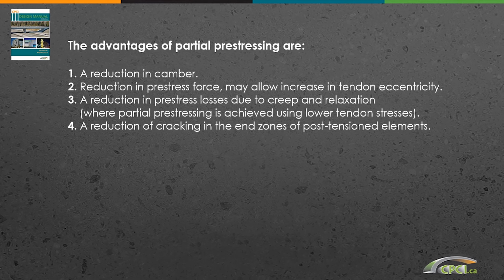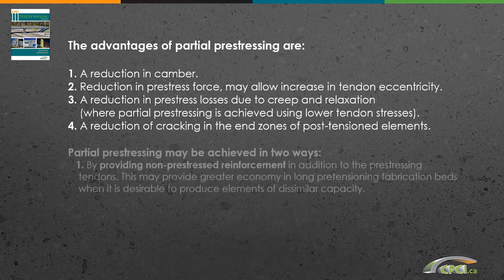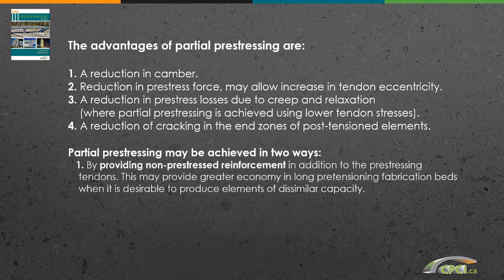That will reduce the post-tensioning cracking at the end zones. And on top of that, it's economical. It's economically advantageous practice, because by providing non-pre-stress reinforcement in the section, you're reducing the cost and also reducing the congestion. And in reality, almost everybody in real life now tries to use partially pre-stressed concrete in everyday practice, as opposed to totally pre-stressed concrete.